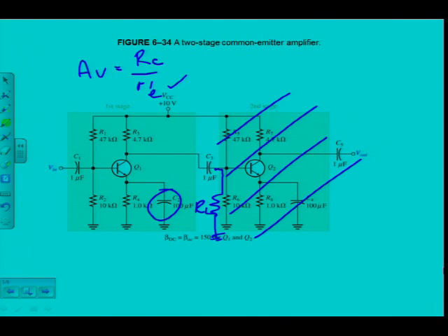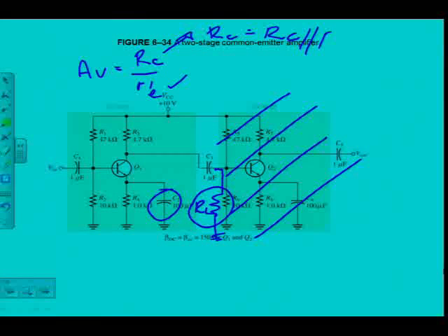Yes. Now let's go on top of the line. What did we say? RC. What do I have to check? When we've done the equivalent circuit, RC would be parallel to our load, if it is present. If there's not a load resistor, then of course this formula would have been true. But now we've seen I have a load resistor, then I had to calculate R lowercase c, small letter c, which is RC in parallel with RL. You agree? Alright. So, now, let's go to the two-stage amplifier here.